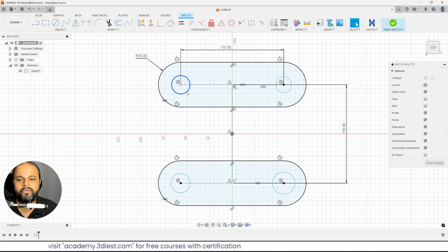Now you can see this blue arrow that is pointing upward. If we drag this arrow, we'll start adding the thickness to it, and you can control the thickness from this box as well. If you want to make it 15, you can just write 15 over here, and this same distance you can also control through this box.